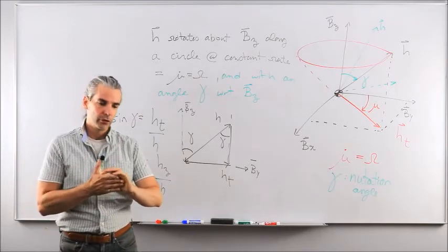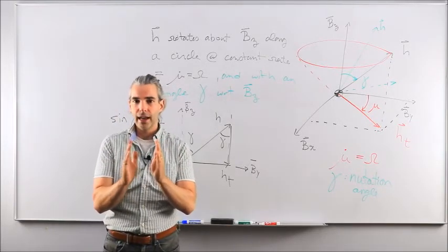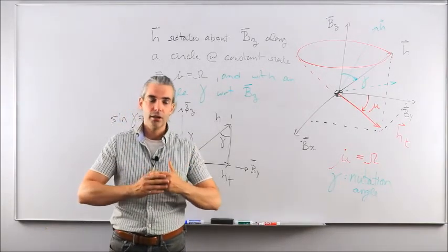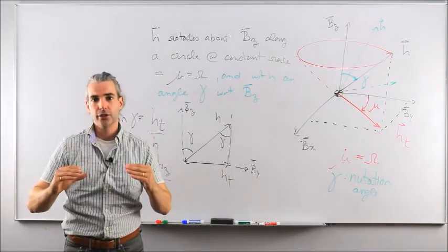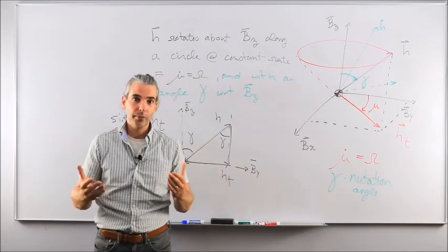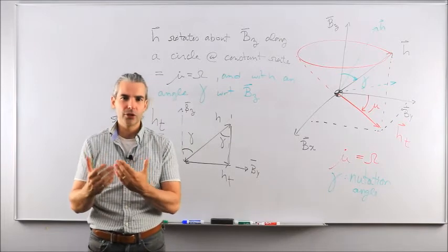That assumption of torque free again is valid for a short period of time because the perturbing torques applied to the spacecraft are low frequency torques and are low in magnitude. Okay, so over one orbit, the effects will be felt quite a bit by the spacecraft, but over a short period of time, the torque-free assumption makes sense.